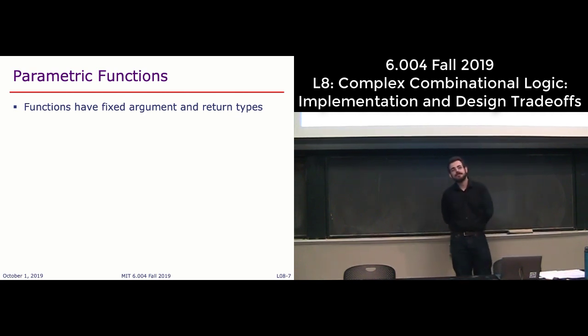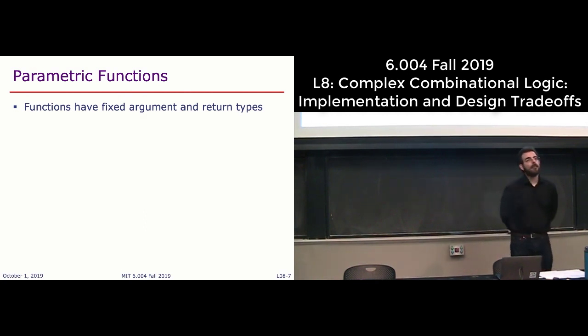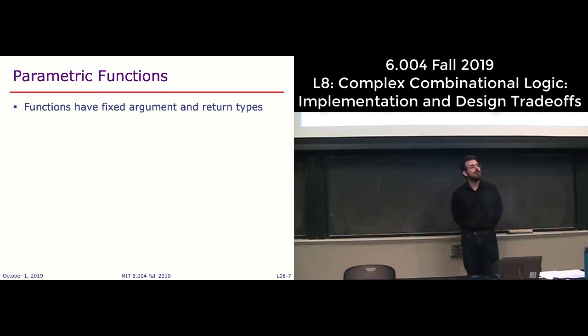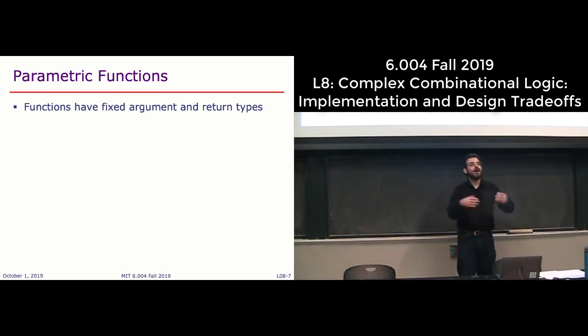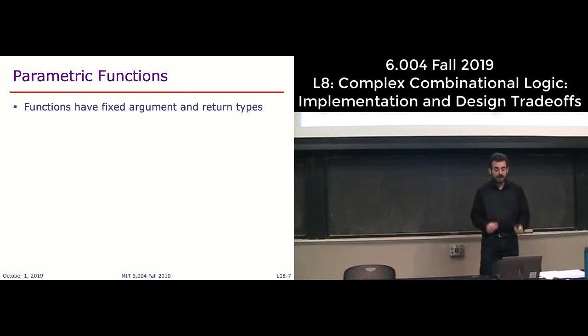It's also very general. Most statically typed languages have some notion of generics or templates. C++ has templates, Java has generics, and so on. So you're going to see this all over the place. But it's actually more important in combinational logic. This concept is far more fundamental when you're building hardware than when you're building software, because in hardware you can do fewer things. In hardware you cannot take some variable number of bits as the input with combinational logic. You just have a fixed number of bits. And this is why it is a much more important concept.